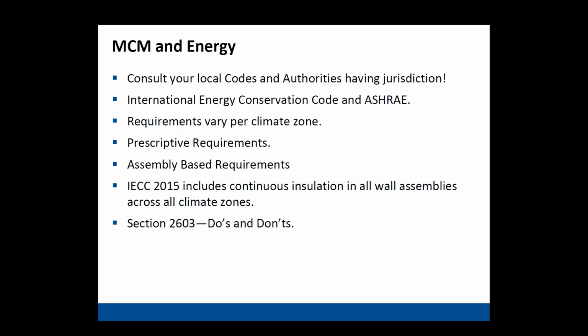Yep. I think that's really important. And again, those non-top shelf fabricators might not understand that NFPA 285 testing means you actually have to have a test of an assembly with all the layers and materials that you're looking at. It's not just a blindfolded throw at a dartboard. It's a very specific test for a very specific assembly. And again, some places will allow for engineering judgments, but not every AHJ will. They'll require a specific test that has your thermal barrier, your insulation, your weather barrier, everything that you're showing in your detail.